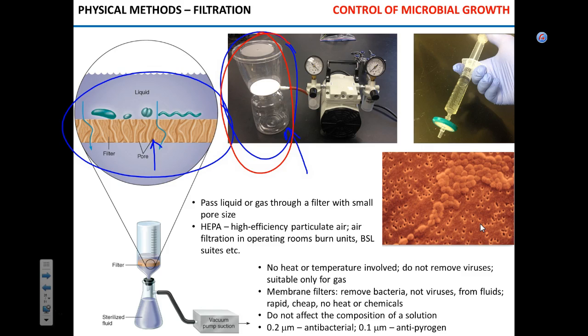So this is probably a 0.22 micrometer filter. So 0.22 retains all bacteria. It doesn't retain fragments of the bacterial cell wall though, which means things like lipopolysaccharide, the toxin fragment of the bacterial cell wall, can still go through, and that's called pyrogenicity. Okay,